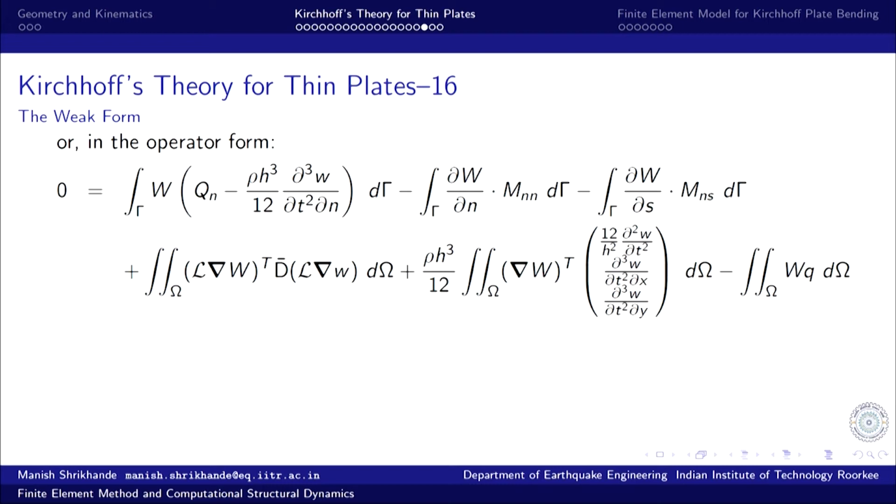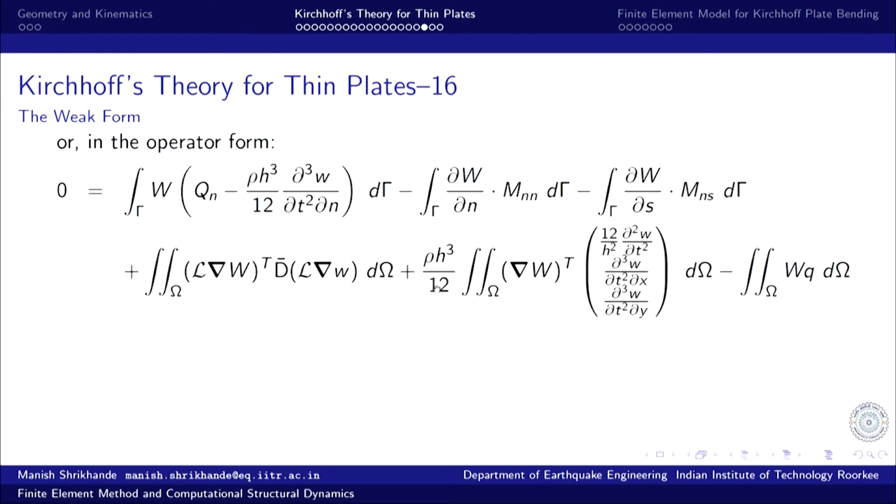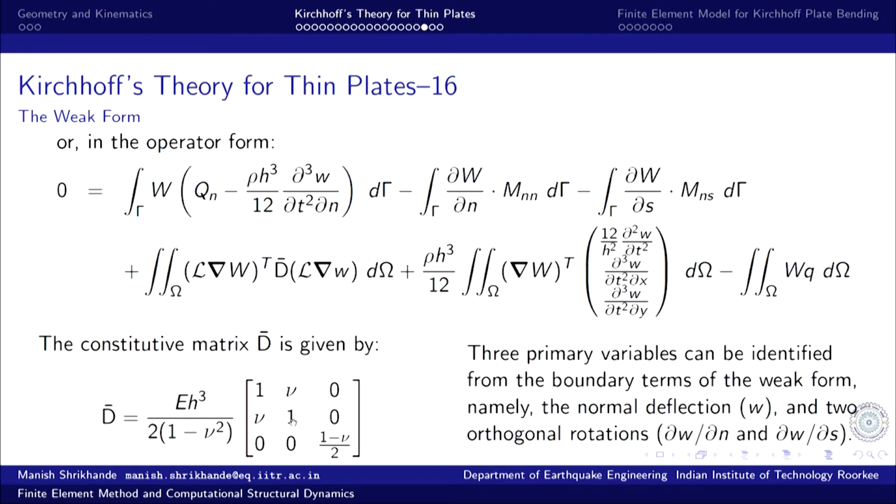Again we can use operator form for a compact representation of the domain integral. This is the compact representation of the domain integral, and this is the boundary integral. The constitutive matrix D is related to plate rigidity and the plane stress model. Three primary variables can be identified from the boundary term: the normal deflection W and two orthogonal rotations, that is del W by del n and del W by del s.